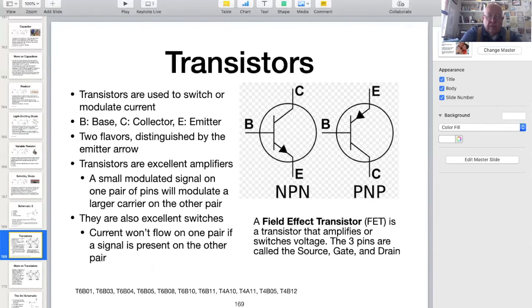That's a long and almost correct explanation of what P and N mean in the transistor type. The schematic symbol for an NPN transistor has the little emitter arrow pointing out, while a PNP transistor has it pointing in. I remember the types by "not pointing in," NPN, or "pointing in pointer," PNP.